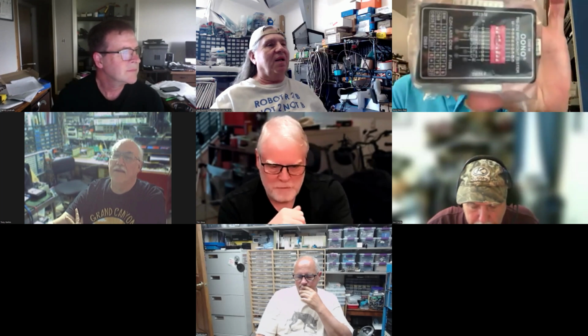That's why I had him just loop back transmit and receive on the SIO board itself, assuming the cable's on the right pins. I had him check that your receive data light should be on along with your transmit light, and if you type a key, they're both blinking. But apparently he can't see the LEDs while he's typing. My computer console is here, and the computer is actually on the other side. I'm trying to just eliminate everything but the SIO board. But that's not the problem.